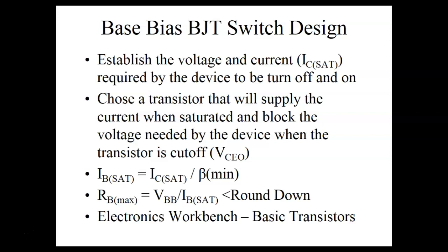What we have in data sheets are these measurements right here. We have what we call VCEO. This is the voltage, collector to emitter, with the base open.